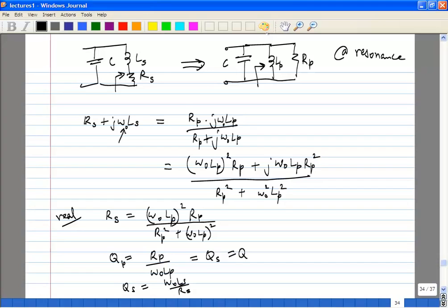Sure, you can do that, but the difference is Q tends to vary a lot over frequency, right? Sure, if you take much lower Qs, you'll get it. But what you would do is, let's say you're going to use this for a certain frequency, right? You would take the Q at that frequency and calculate this network at that frequency. What happens is, remember, if you just take the overall input impedance of this, and you try to convert it to look at the real and imaginary parts of, let's say, the admittance, they are going to be frequency dependent.